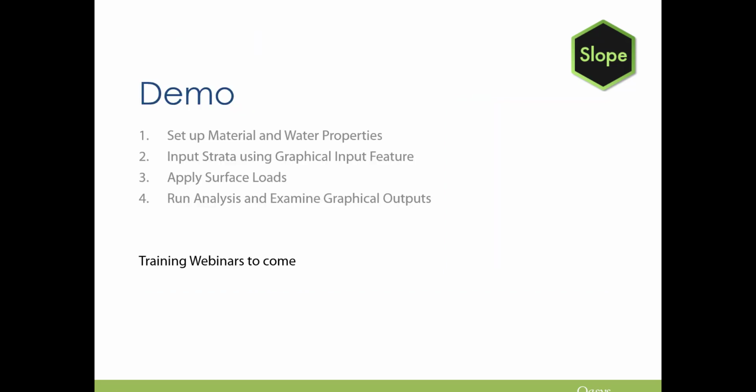So I'm going to run a demo now to show you how to set up the material and water properties with the new interface. We're going to input strata using the graphical input feature. We're going to apply some surface loads, so keep it really simple, and run the analysis and examine graphical outputs.